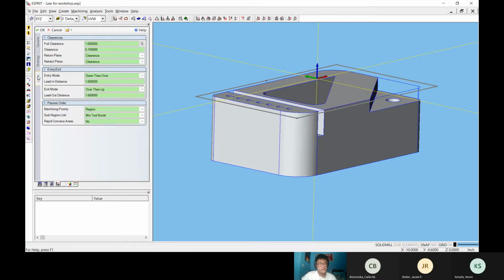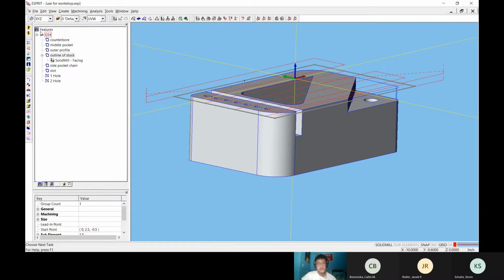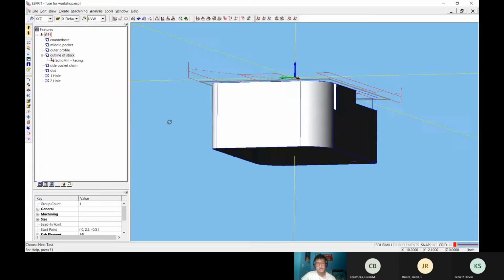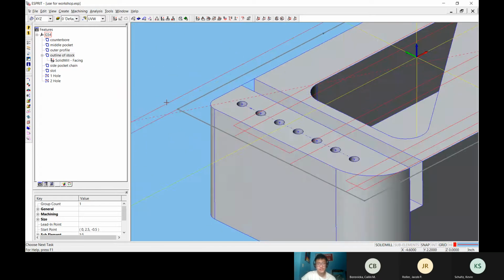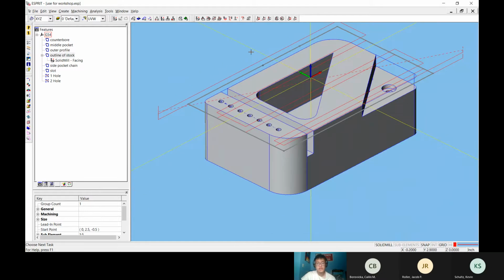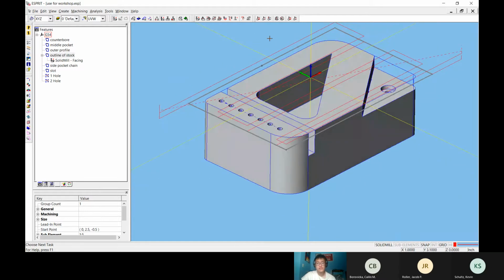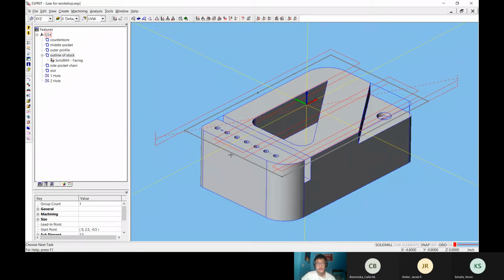And then usually there's not too much for links. We're not going to really cover much about the links tab. So we're just going to go ahead and press OK. Yeah, so that is what you should see. Red solid lines indicate a line where the tool is actively rotating and therefore cutting into the material.